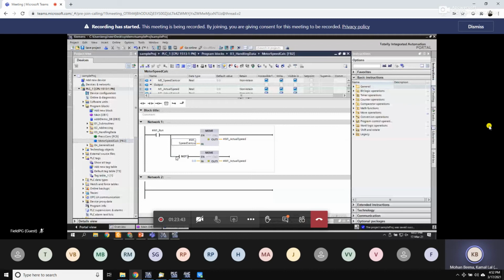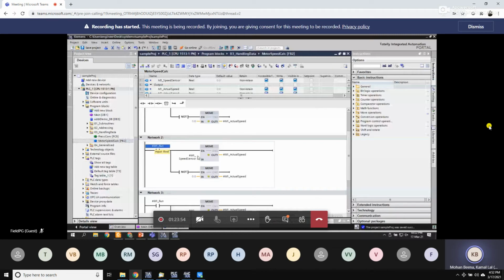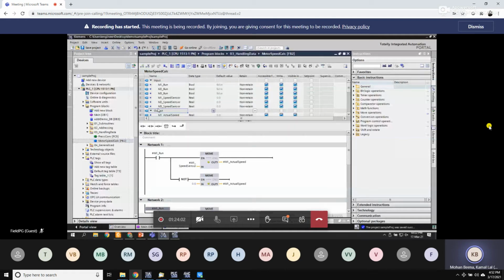I just copy paste it 3 times. That same network I wrote here, I copy pasted 3 times. Now everywhere I have to go and change that M1 to M2. Even for that you have some options. If you see here, the naming convention I have used, I'm always following a particular structure, and there was a reason behind that. Since I have followed this, I know that between network 1 and network 2 the only naming change is that everywhere M1 is there, it should be changed to M2. Then my second network is ready, right? That is possible since I followed a standard in creating the block interface and the naming.